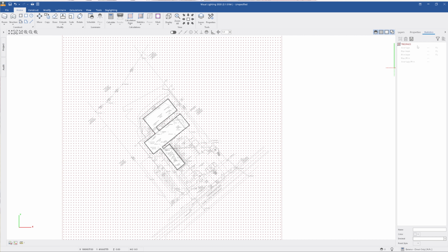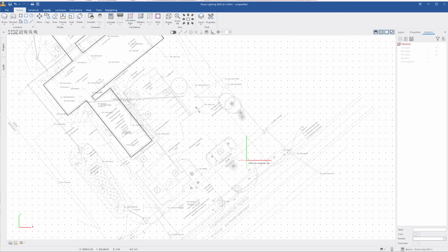Now, for calculations for most of the townships, we are required to show what it would look like on the paved or pedestrian area. In order to do that calculation, we need to create a statistics zone. These are the trickiest things to create because again, it's a one and done type of situation. You have to try to exclude any of the landscape islands or anything like that in your creation. So it can get a little tricky.